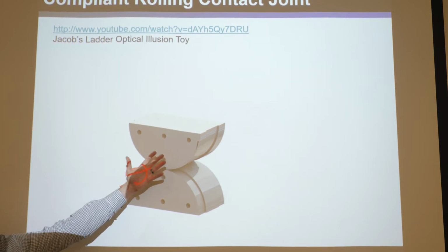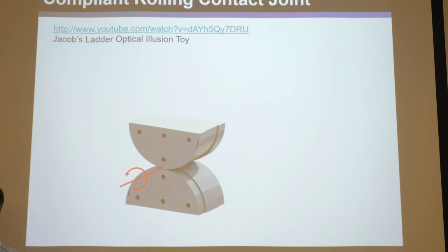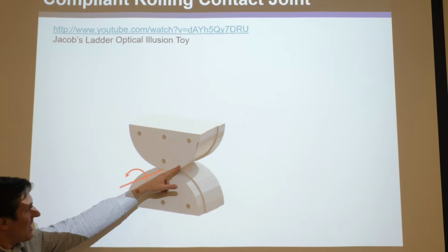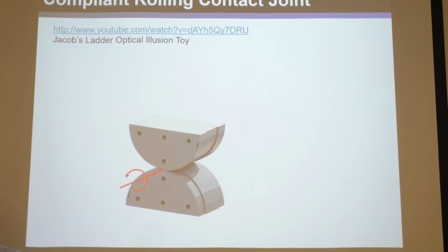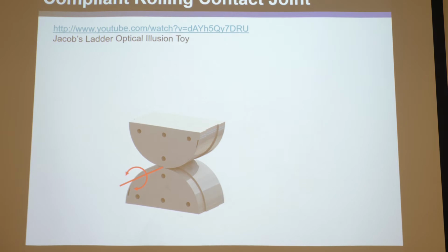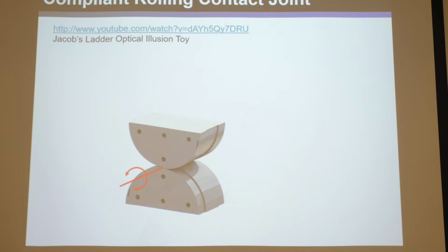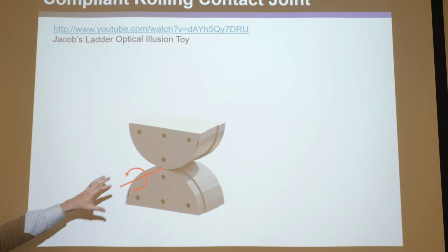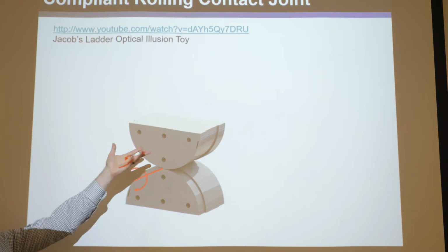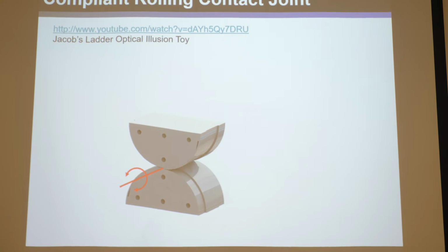And I know that's impossible. It's impossible with a zero stiffness joint. And in truth, to assemble this, you need to stretch these straps a little bit to hold it firmly together. And once you stretch it, you do add some stiffness. But theoretically, if you were able to make them the perfect length and assemble it without anything going wrong, these would have zero stiffness. So you can get zero stiffness joints that are very stiff in all unwanted directions and move 360 degrees without breaking.